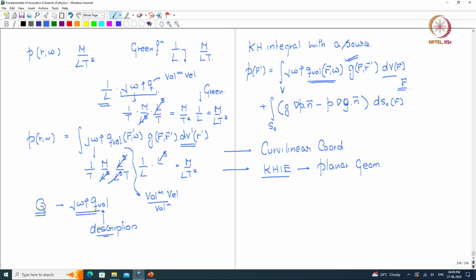Here we found a new Green function which has twice the value of the free space Green function, but it has del g by del z equal to 0 on the symmetry plane. And using this we looked at the piston in a baffle, which demonstrates typical exterior sound behavior.